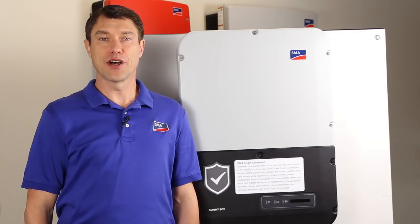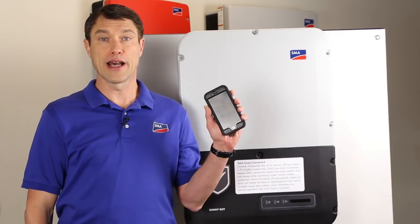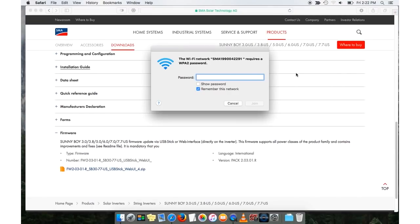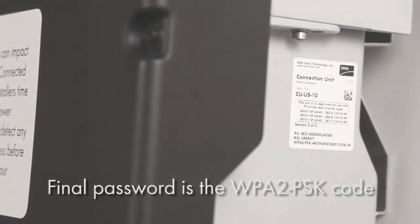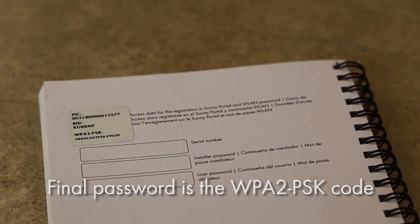If utilizing the inverter's self-hosted Wi-Fi network, any device that can join a Wi-Fi network and run a web browser will work. However, ensure the device you plan to use can navigate to a file and select it. Currently, iOS devices do not support this feature. For access using the self-hosted Wi-Fi, the network name is SMA followed by the 10-digit serial number of the inverter. The password for this network is SMA12345, no spaces, for the first 10 operating hours or until the inverter is first commissioned. After that, the password becomes the device-specific password printed on the label on the connection unit and also on the back of the installation manual.